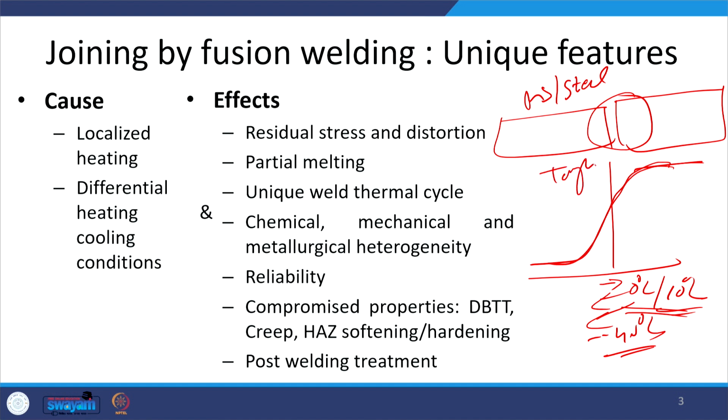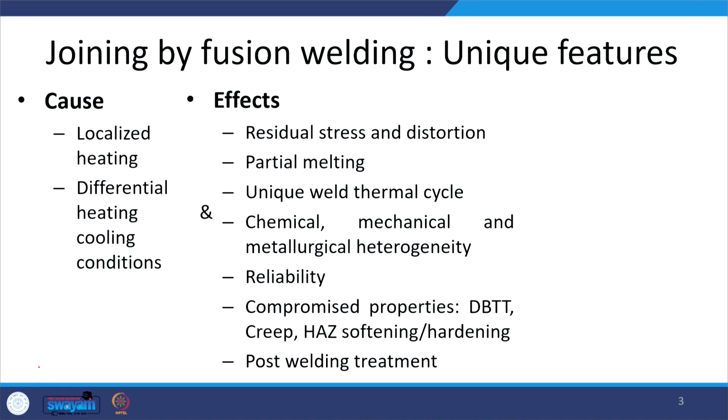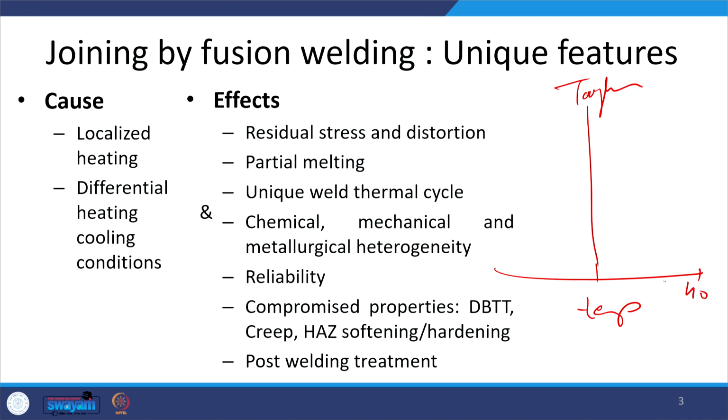So, on the y axis here we have toughness and on the x axis we have temperature, increasing in this direction. I will redraw this. So, on the y axis there is toughness, and here we have temperature, say plus 40, 30, 20, 10, 0, minus 10, minus 20, like this. So, we may come across a variation of this kind. This is one variation, where the drop is experienced between minus 10 to 0 or so.